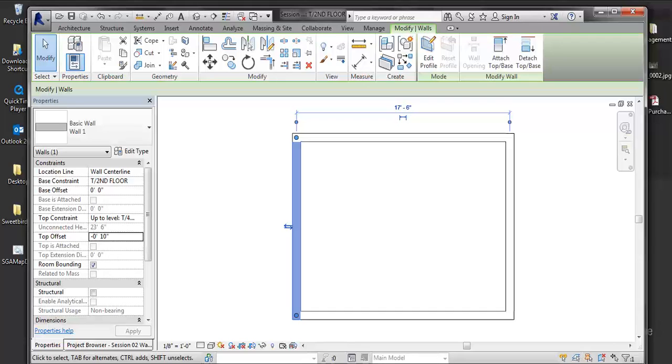And I can offset, just the way I can offset to make up for the slab edge or the slab thickness, I can make up for a base offset if I chose to do so as well. Say I lay a structural floor and I'm actually building this out, my floor in layers, so then I'm doing my finish as a separate floor assembly. There may be cases where I want to have that offset from that base level to actually have my finished floor go underneath the wall or vice versa, not go underneath the wall.